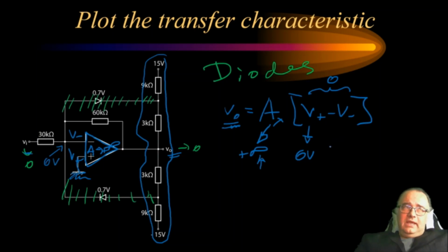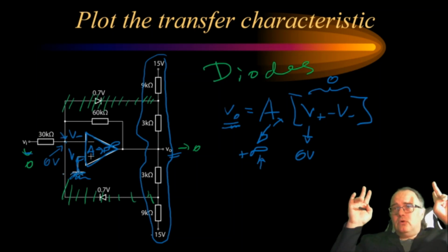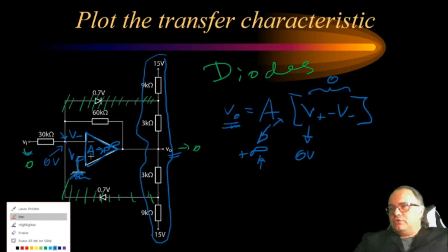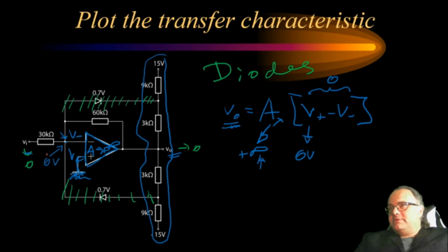And we say that with such a negative connection, the inputs are virtually connected, which means that if one of the inputs is ground, then this node here should be at the so-called virtual ground, or 0 volts, or something extremely small. For all practical reasons, we can assume this to be 0. And now it's very easy to get the relationship between the input and the output.